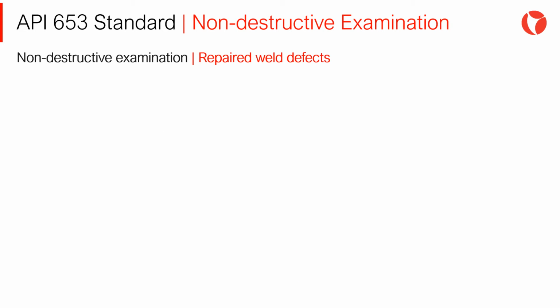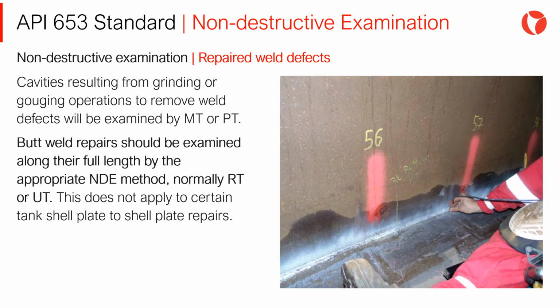Repaired weld defects. Butt weld repairs should be examined along their full length by the appropriate NDE methods, normally RT or UT. This does not apply to certain tanks' shell plate to shell plate repairs.